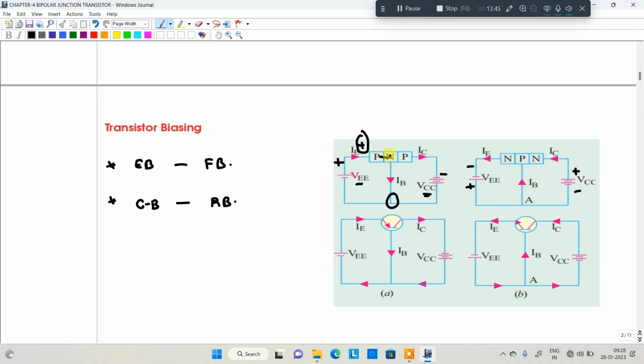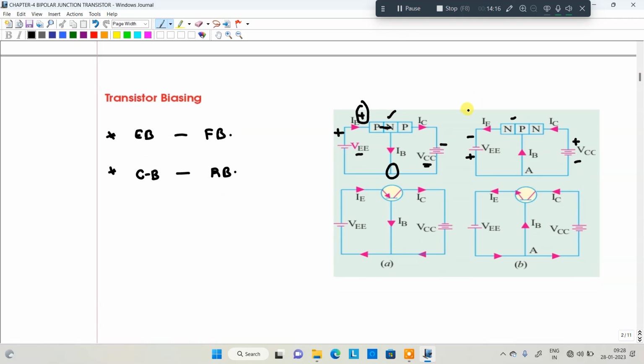What about the negative electrons? What are the majority charge carriers in the base junction? They are the electrons, trying to be attracted out towards this positive terminal. That means recombination of electron-hole pairs is taking place. Whatever free electrons remain cross over this particular barrier, this junction, and try to flow. This is the way in the N-type material also. I hope you got an idea about why you connect positive on the input side and negative on the output side in the case of a PNP transistor.